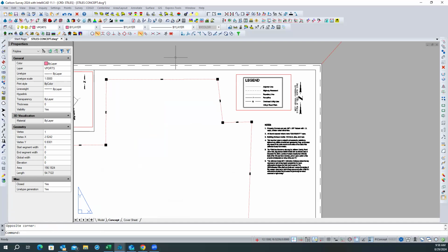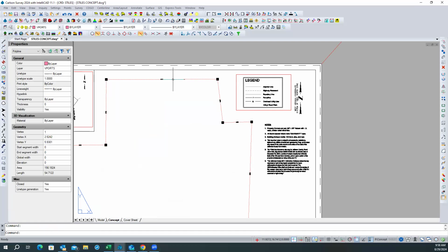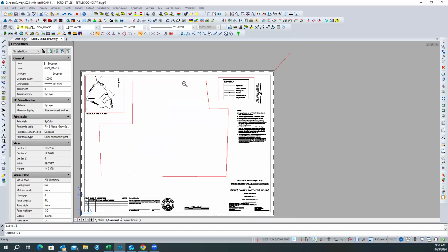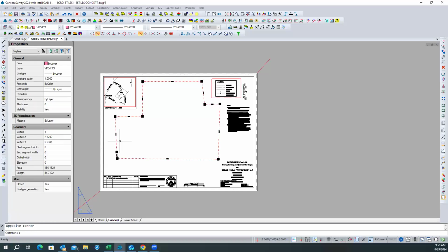That other viewport was keyed to that polyline, and all we did was edit the polyline. But I'm no longer picking that up. See, it's just the polyline. So what I'm going to do, get rid of that extra I don't need, is I need to make this into a new viewport because right now it's not.